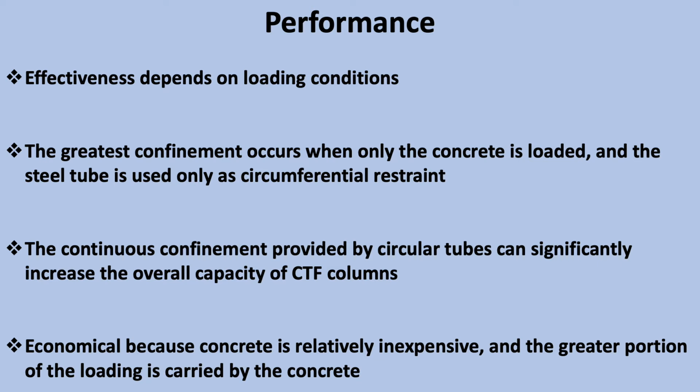Studies have shown that the effectiveness of CFT columns depends on the loading condition. And it has been shown that the greatest confinement occurs when the concrete itself is loaded and the steel tube is used only as a circumferential restraint.